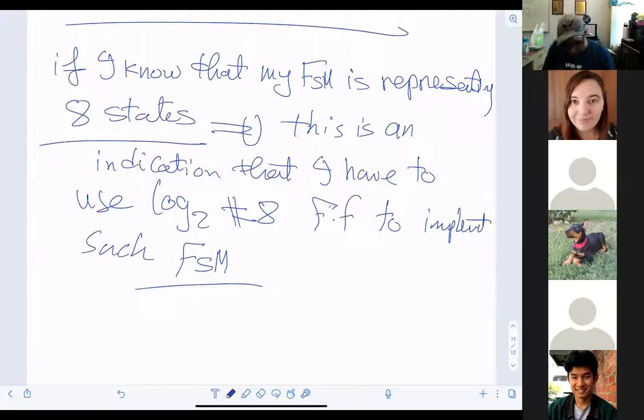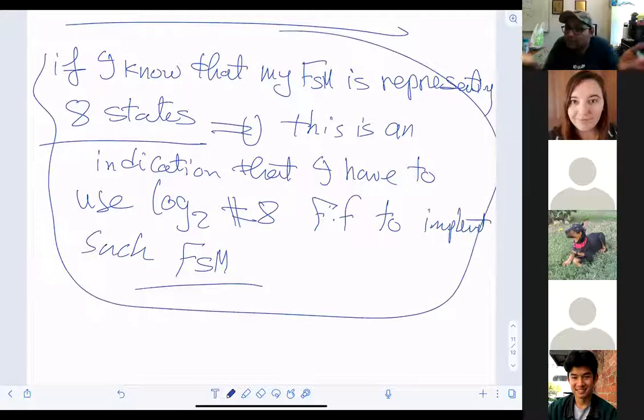Whatever flip-flops. Look, this is general stuff, right? It can be any flip-flop. That's opening the door about how you can make the implementation. But now I'm not talking too much about implementation. I'm talking about something called graphical representation. Later on, we're going to move into a scientific way. Do you remember the theoretical way I followed with you to move from flip-flop to the others? I'm going to write down steps like that too, but at least I want you to think about it. State machines represent the sequential circuit behavior. A state machine is a graphical representation telling me what is the next state based on the current state and the input. Do you agree?